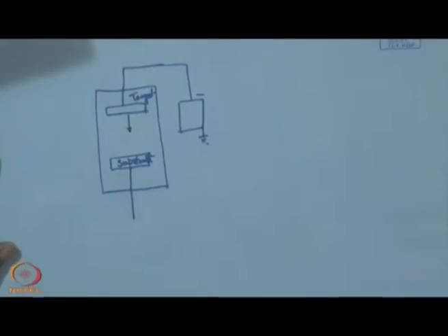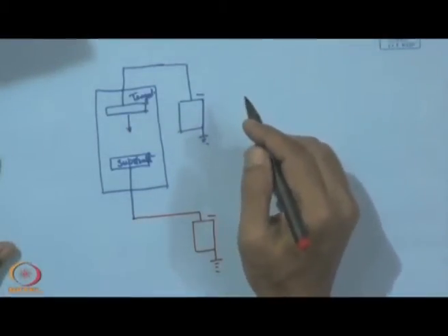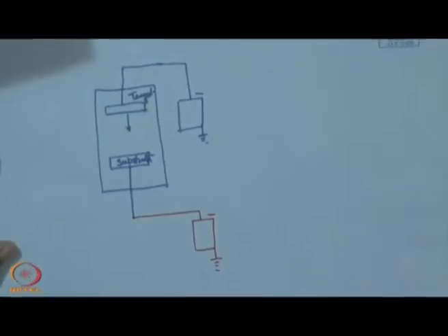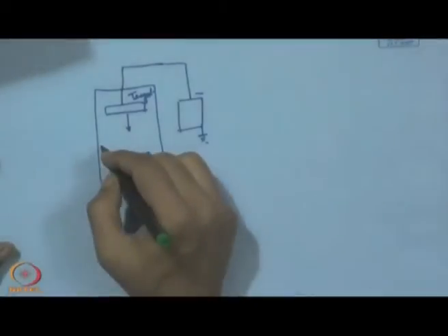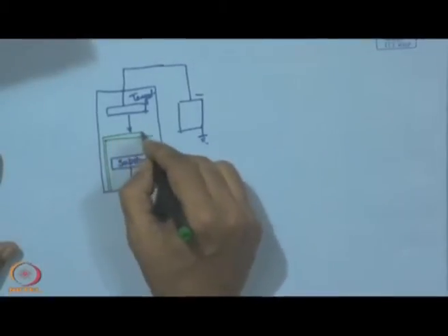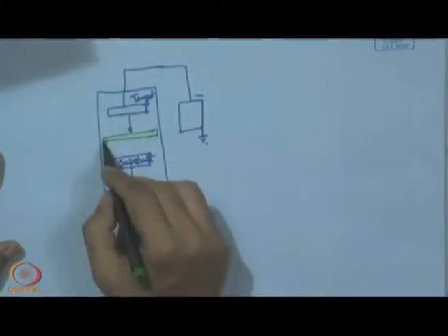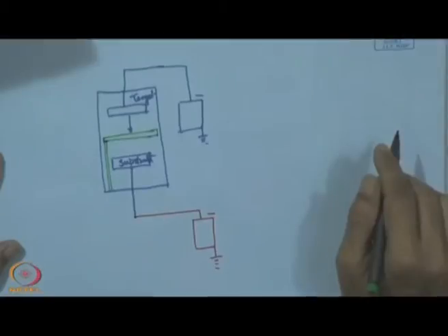Now, what we can do further is that this substrate can also be polarized. That means it can have a negative polarity which is independent of this power supply, and in between we can have a plate which is called the shutter. The whole idea here is to have the best possible clean substrate and clean target.